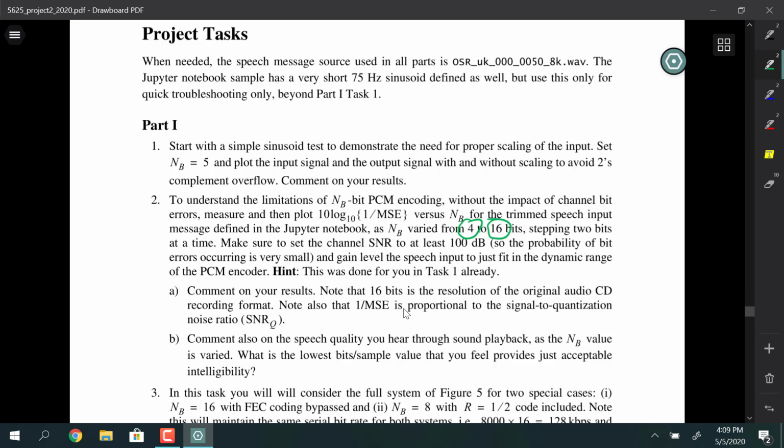And you're going to get an output signal to quantization noise ratio that just linearly steps as you increase the number of bits. As you go from 4 to 5 to 6 to 7 to 8, it'll just change by 3 dB per bit, I think is the number. And when you collect the data, you get just a perfect, really nice straight line. It's just sloping upwards. And if you listen to compact digital audio, you're listening to encoding with 16 bits. And if you're listening to telephony, it's about 7 bits on the cellular network, on the telephone network.